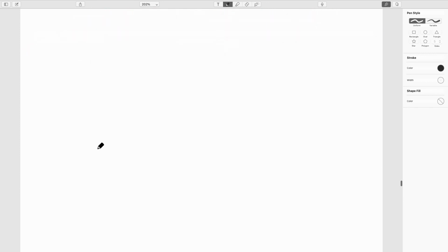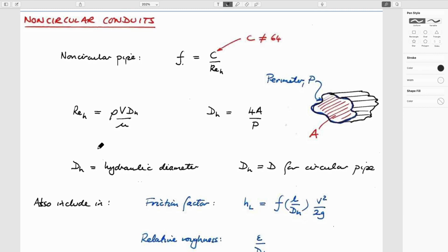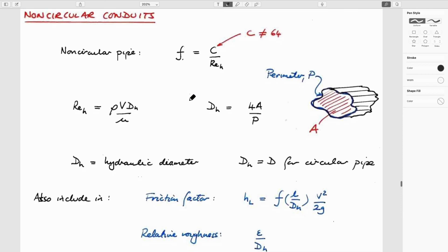So that's a diversion. There is a question in the test that talks about work done, actually there are parts of two questions that would impinge on that, so you have access to that. All right, most of the pipes that we've talked about have been circular section pipes, in which case the friction factor for laminar flow, this coefficient, has been 64. And that's probably not going to change very much.